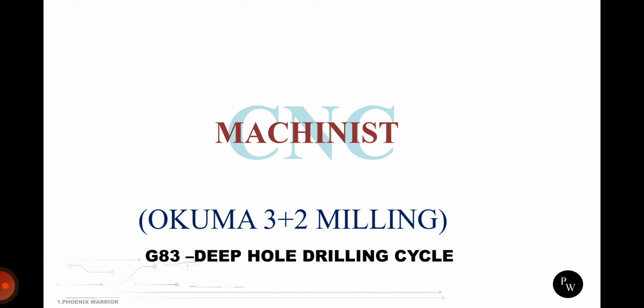The difference between the spot drilling cycle and the Peck drilling cycle is that the material removal rate in the Peck drilling cycle is high because it goes to a longer distance. The purpose of spot drilling is making a starting hole for further drilling. In peck drilling we make a pecking motion in the hole.